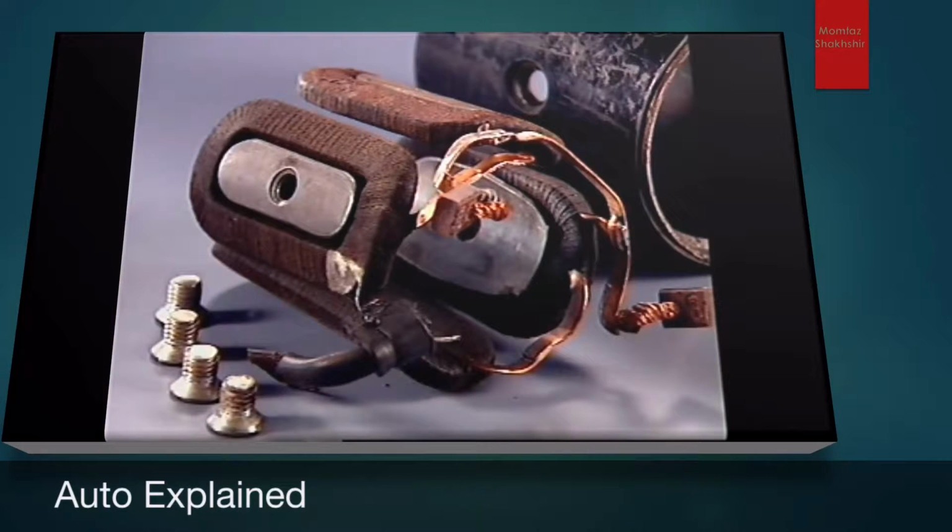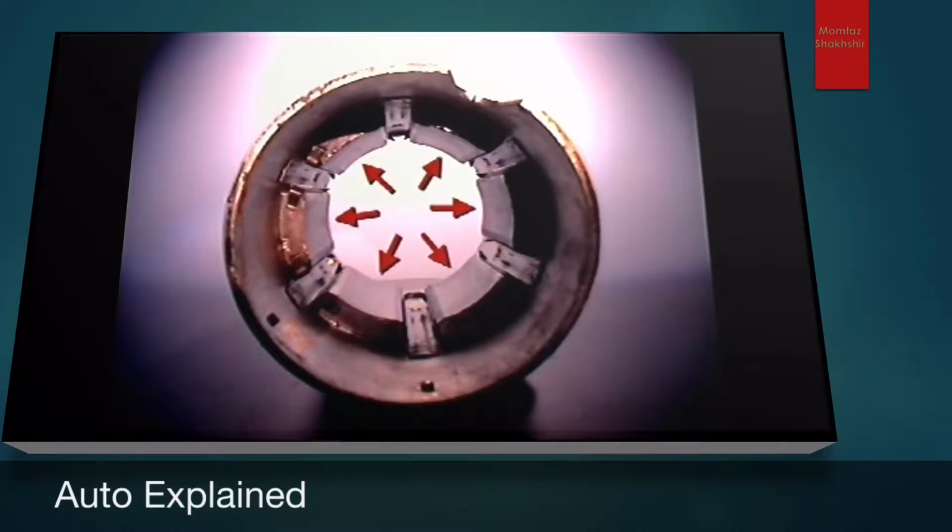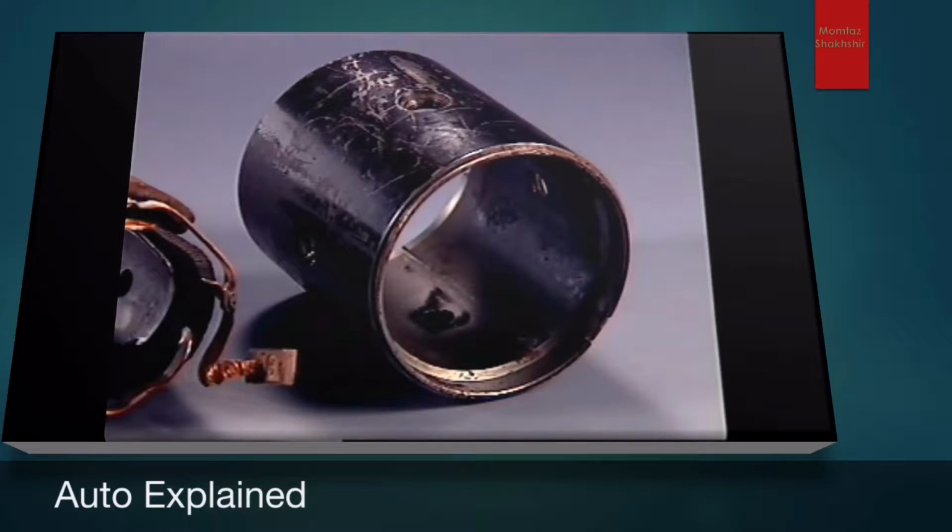The electromagnets are formed by current flow through heavy strip copper windings, wound around iron pole shoes which are fastened to the yoke. Permanent magnets are located similarly, but occupy less space. The yoke is made of iron and serves to concentrate the magnetic field produced by the field magnets.